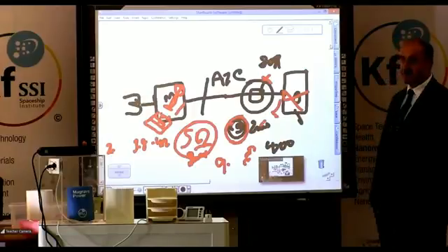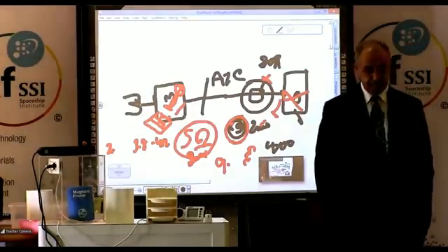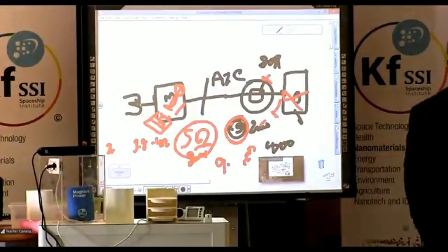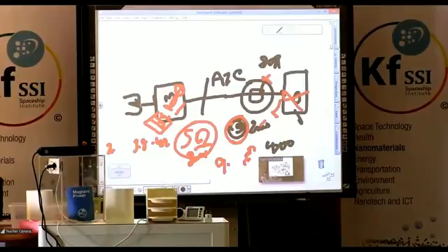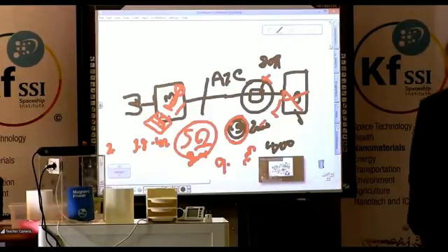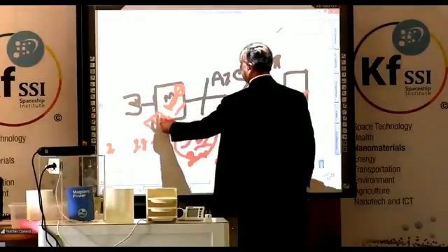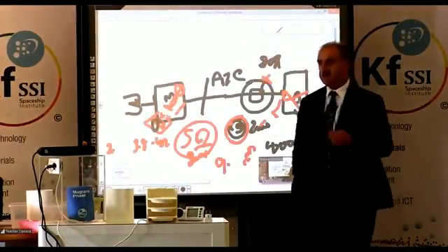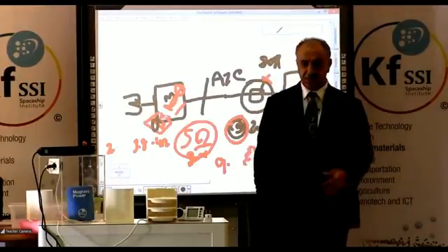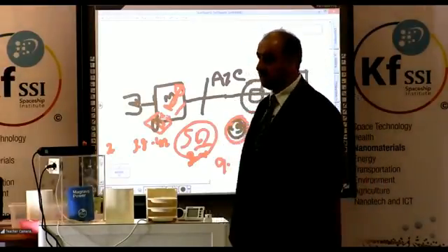Any other question? Somebody had a question from the first session today, regarding the thermal overload protection. Eugene was asking, will a freezer thermal overload protection work? The overload protection is just by heating, because the only thing that will happen is the copper gets heated, and we have put a 55-60 degree circuit breaker that if you overload it, the supply cuts off, and you see your heater doesn't work. Then you let it cool down, reconnect it, or take the load you had off it. You'll find out